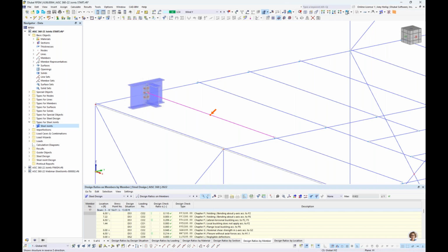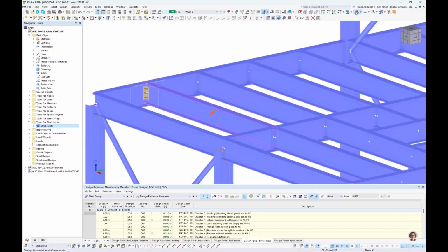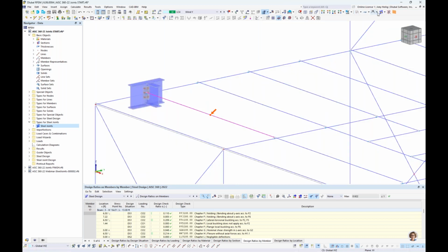You also have the ability here, if we go back to, I'll keep this in wireframe view, you'll notice that we have a new option here to show no joint model. If we wanted to completely hide it, we also have the simplified option here, or we can go ahead and keep it as a detailed joint model.